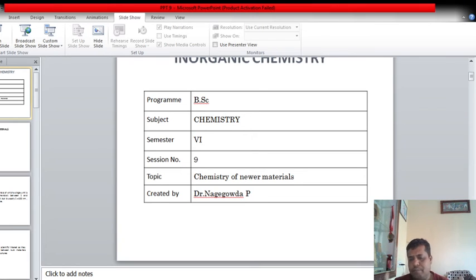The materials we have are different materials having different compositions, but using the sol gel method we can make a product having a proper chemical composition. In addition, we can add small quantities of dopants. That means organic dyes or rare earth elements can be introduced into the solution and end up in the final product finely dispersed.